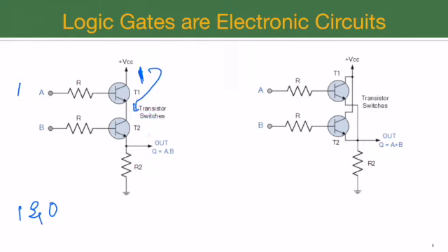So let's roll back a little bit more and see if we perform this operation in the reverse direction. I want to perform an AND between 0 and 1 instead of 1 and 0, which means that I have applied a 0 over here. If the 0 is applied over here, this value 1 will not get transferred over here, and the value over here will remain 0. Next, I have a 1 input over here.